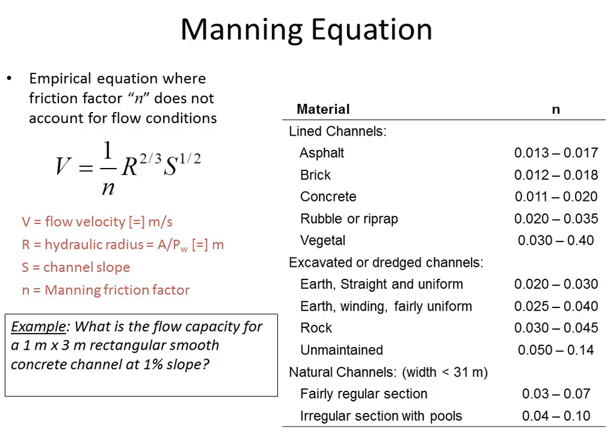And in this case, the area is still 3 meters squared, but the wetted perimeter has changed, right? We've got more wetted perimeter now. We've got 3, 4, and another 3. So the wetted perimeter is 7 meters. So the hydraulic radius is going to be 3 meters squared divided by 7 meters. I haven't got my calculator. What is it? 0.43 meters.